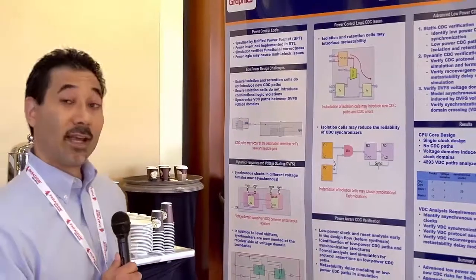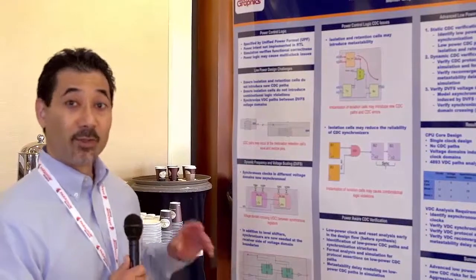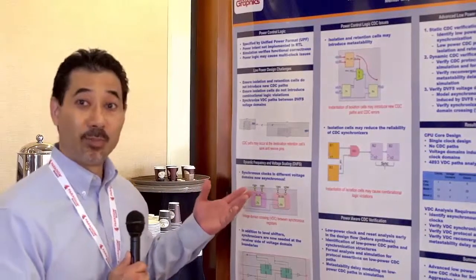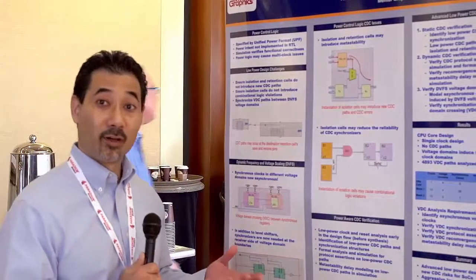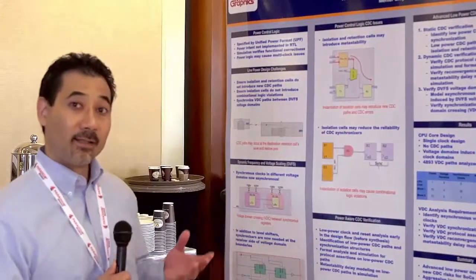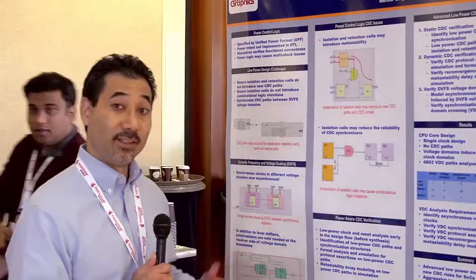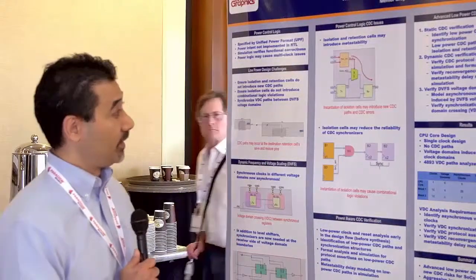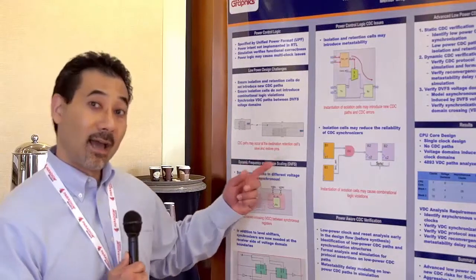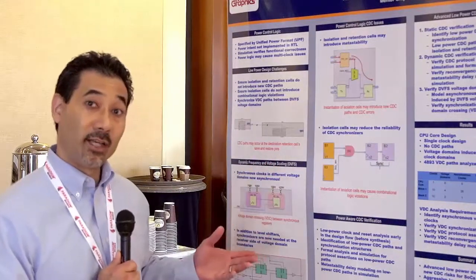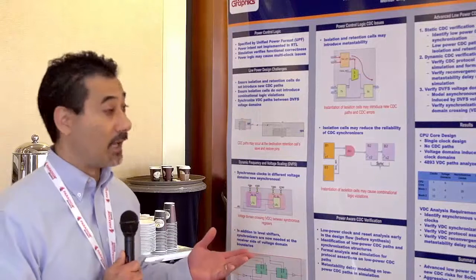And what we're seeing is that with today's RTL design, there's some design information contained in the UPF files. And this information can be used with the RTL to verify designs for any CDC issues. So some of what we're seeing is that typically design teams are looking at having the isolation cells modeled in RTL and verifying those paths for CDC analysis.